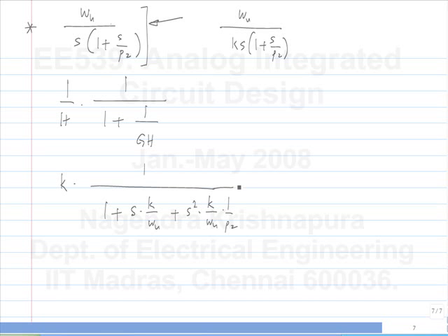Now again, whenever you evaluate something like this, which is an extension of an earlier case, you should do a sanity check to make sure that the answer is right. So what's the boundary condition here you can use to check that? If P2 is infinity, it should go back to the earlier case, and it does, right? So this term vanishes if P2 is infinity. So what can you say about this? We have a second order system, so what about it?